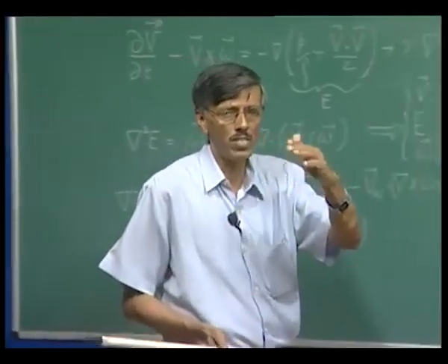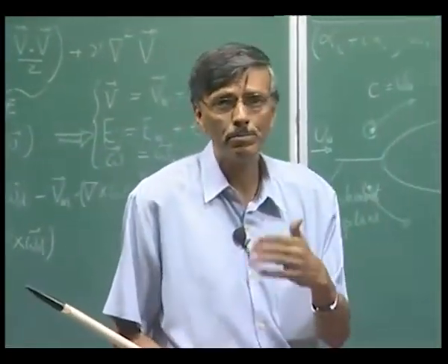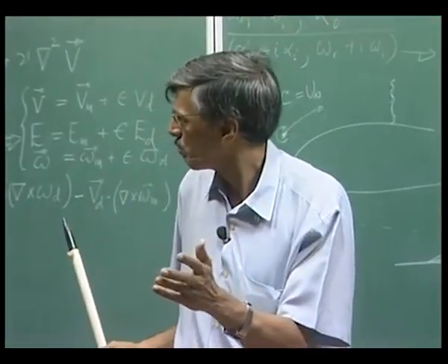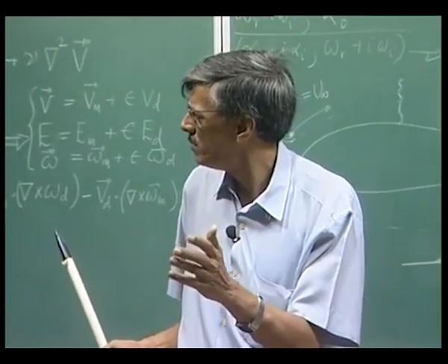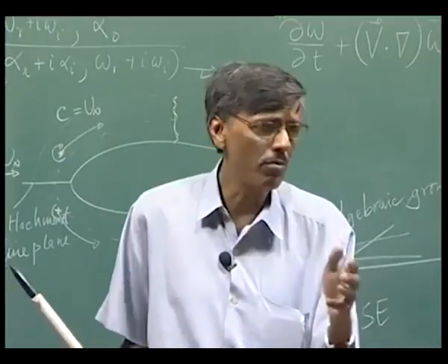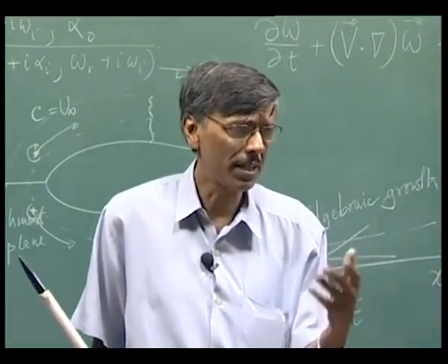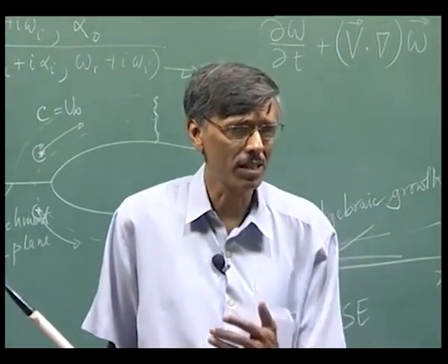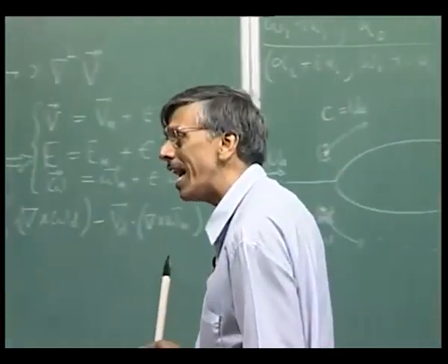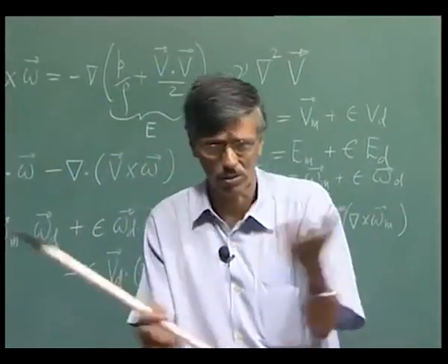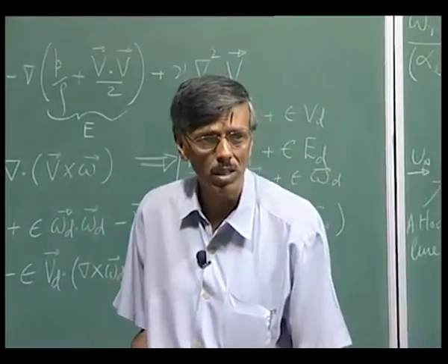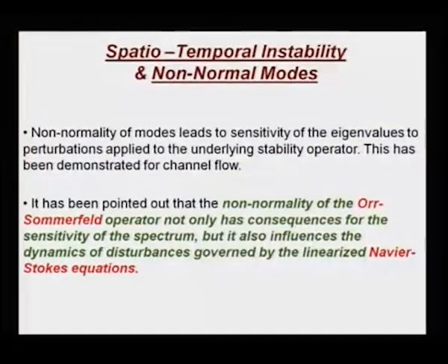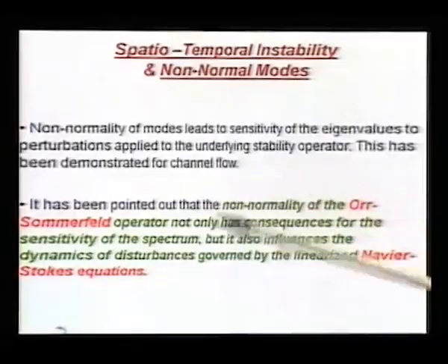In the case of linear theory, we saw that the critical Reynolds number was 5772, but we know experimentally it can trigger at much lower values. There it could be that the flow is not a so-called uniform flow, it is coming with disturbance. Those are hypersensitive to disturbances. That kind of flow has been reported in Schmid and Henningson's monograph on this flow.